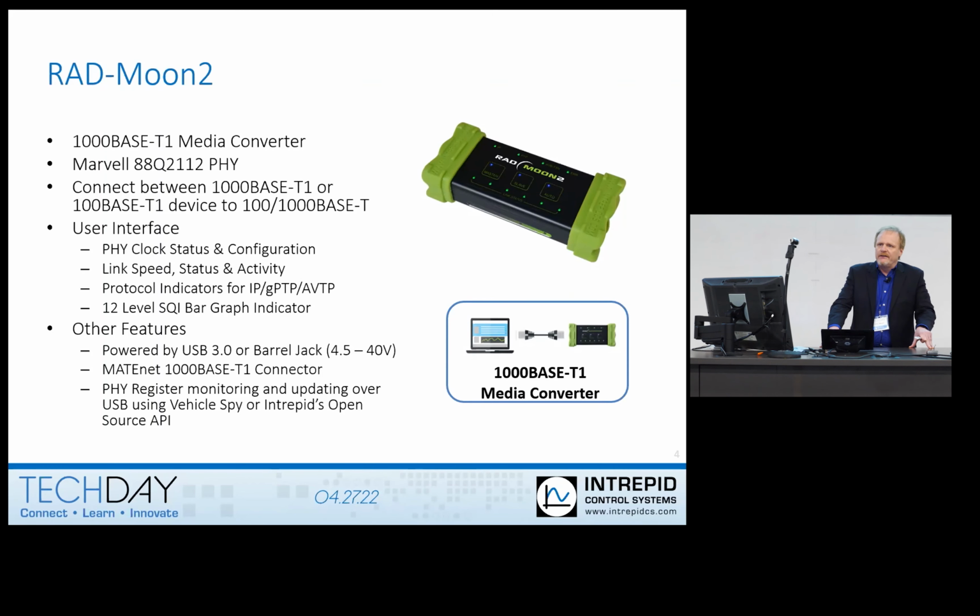And so with this, you can read things directly, like the signal quality index. You can read error counters. So yeah, signal quality, link status. There are also some registers in there to tell you time to link and different stages of the linking process as PHYs connect with each other.